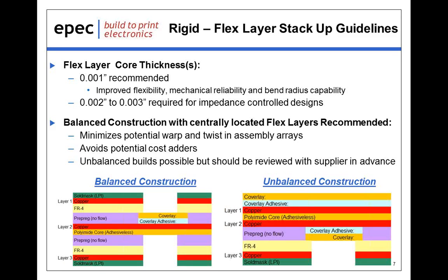As you can see from the two images below, which are both based on a 3-layer construction, the leftmost is a balanced one where the flex core is located exactly in the center of the stack-up, and the other is an unbalanced one where the flex core has been moved up to the top. As I mentioned, both are indeed doable. A balanced construction is always preferred.